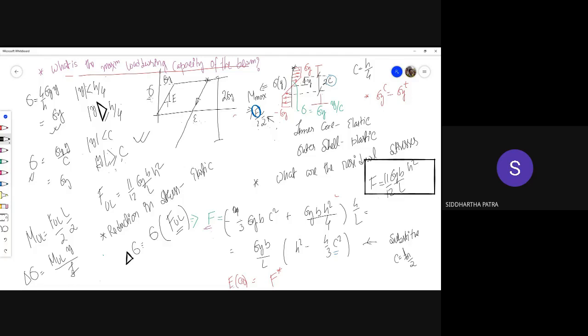So you understand, right? When I'm doing a uniaxial tension, everywhere on the cross section, it's the same stress. And then when I remove the force, everywhere in the cross section, you end up having the same stress, and that stress is zero because the total force is removed. Okay, but such is not the case with bending, because in bending, within the cross section, the stresses are different.